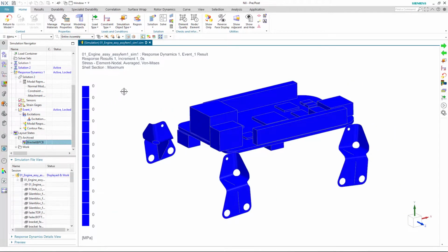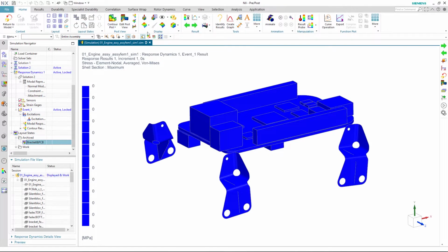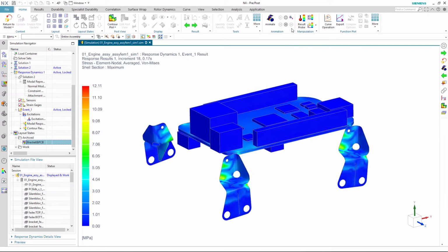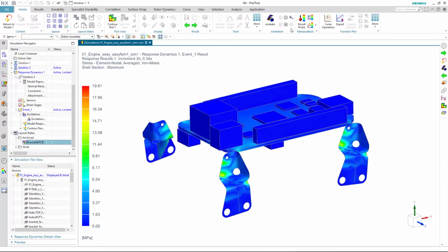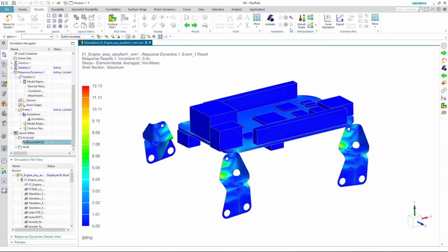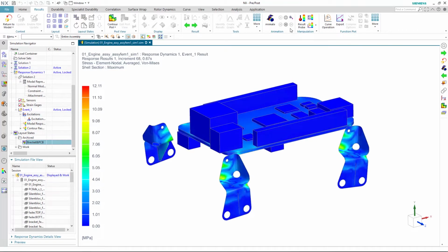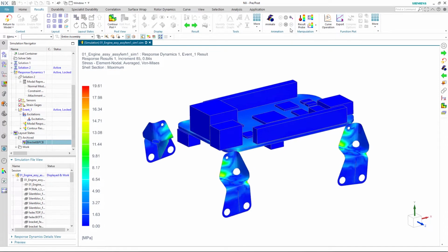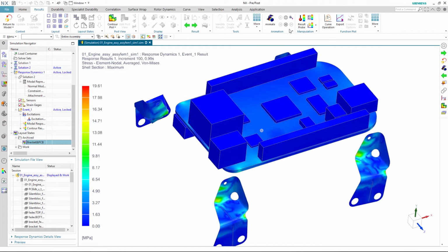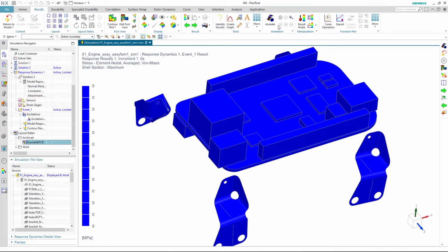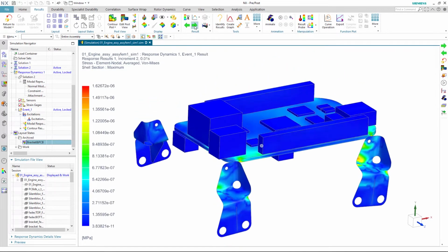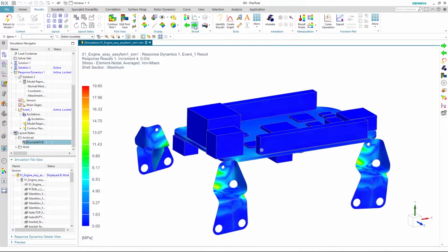After the solve, we can directly open the results on the same user interface and define post-processing activities. At this stage, we were able to define the mechanical stress on the bracket and the acceleration on electronics components. Transient von Mises stresses are predicted and shown in the support brackets on the PCB. The analysis identifies where the increased stresses are located so that remedial action can be taken.